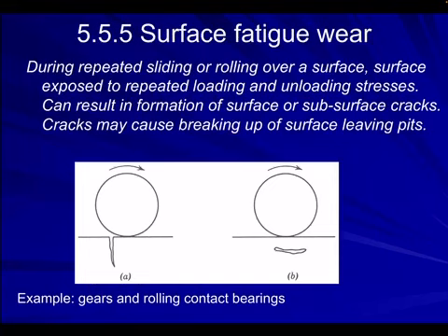Surface fatigue wear, this happens during repeated sliding or rolling over a surface, and the surface is exposed to repeated loading and unloading stresses. It can result in the formation of surface or subsurface cracks. So that would be a surface crack, and a subsurface crack will be here. And cracks may cause breakup of the surface, leaving pits. So we typically see this with gears.